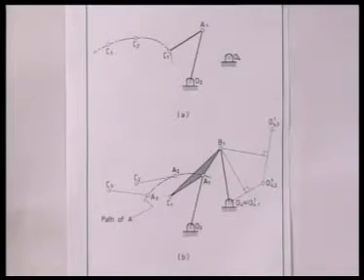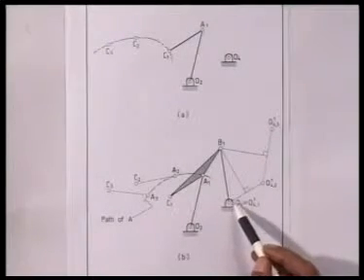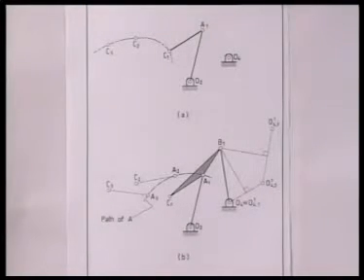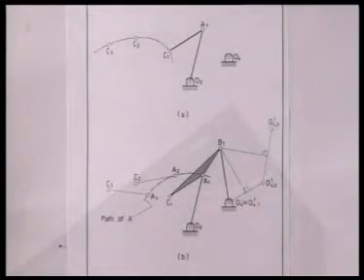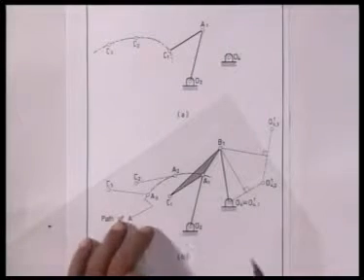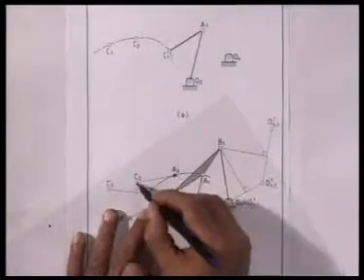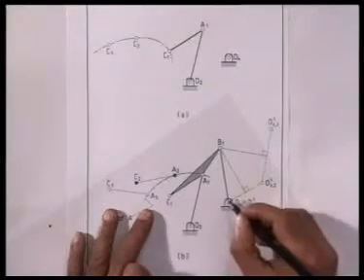So from these given locations C2 and C3, I can determine A3 and A2 because AC is of given, fixed length. To determine B1, what we did, we considered the inverted positions of O4. To obtain the inverted positions of O4, I hold the coupler fixed at its first configuration, that is A1C1. Corresponding to the second configuration, we marked A2, C2 and O4.